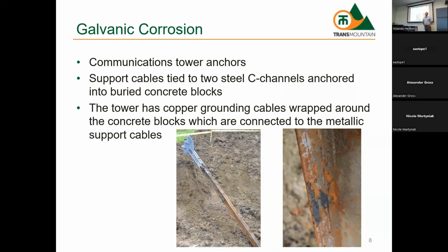If it would have been immersed, it would have been protective. Okay, valid point. Because there's no connection. But this was zinc too. This was all galvanized. Yeah. But this was completely consuming the zinc because it was in the soil where there is moisture.